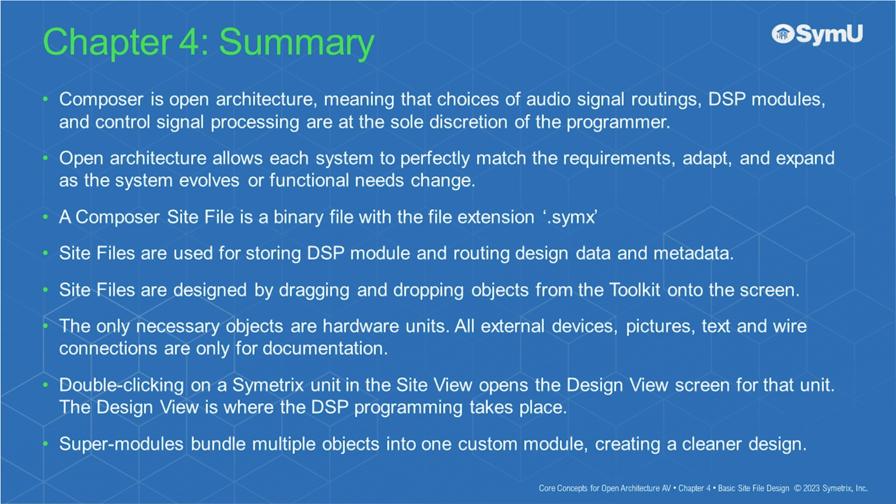Double-clicking on a Symetrix unit in the site view opens the design view screen for that unit. The design view is where the DSP programming takes place. Super modules bundle multiple objects into one custom module, creating a cleaner design.